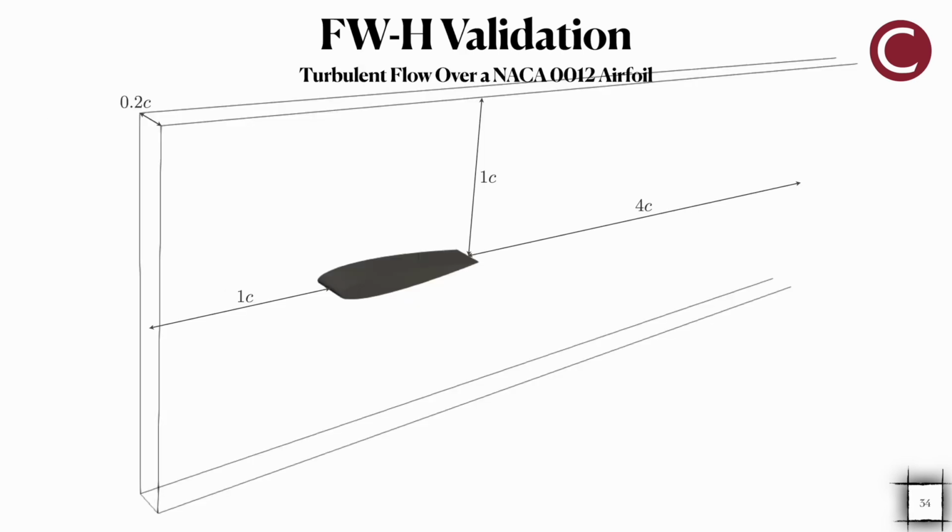So we ran the NACA 0012 airfoil, and the observer was located 2 chords below the trailing edge. So we first used the direct approach, meaning that we ran the CFD simulation on this airfoil and compute the sound at 2 chords below the trailing edge in the near field observer. And we also used our acoustic solver.